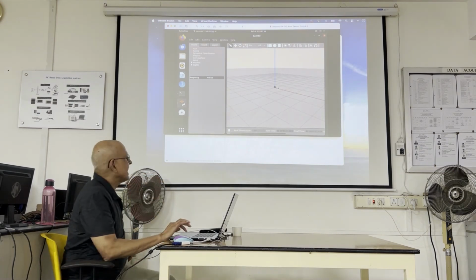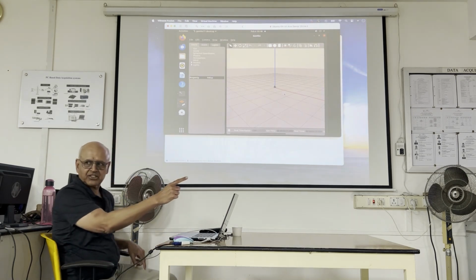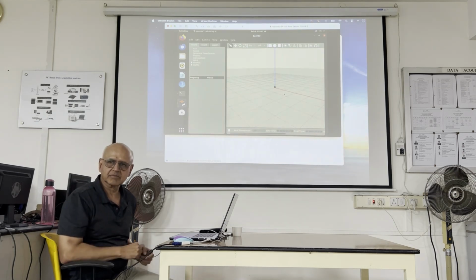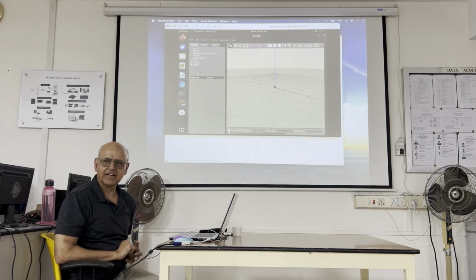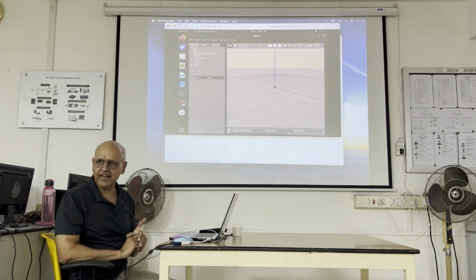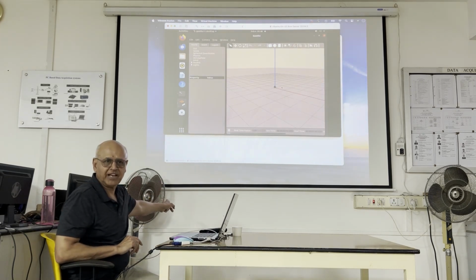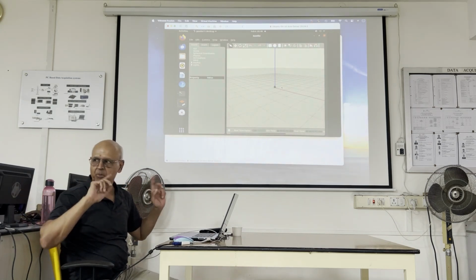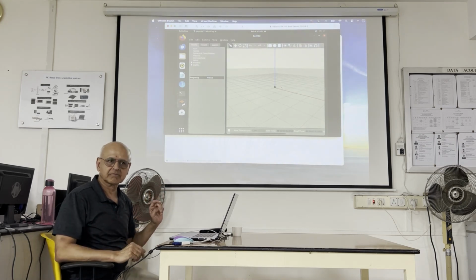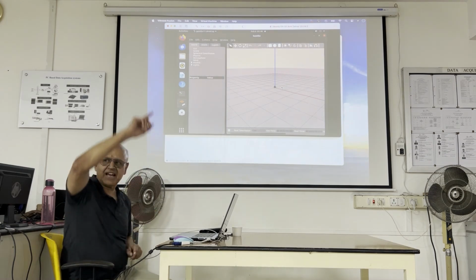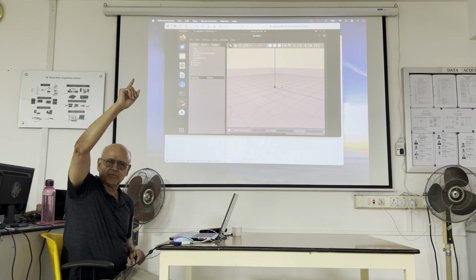So, what you're looking at is the world axis here. Now, red is the x-axis direction. That's the convention. It's always through the nose of the robot pointing forward. So red is the x-axis. Green is the y-axis. It's always to the left, not to the right. It's not take your choice. The robot convention has nailed it down. Left is y-axis. The z-axis is pointing up, not down.